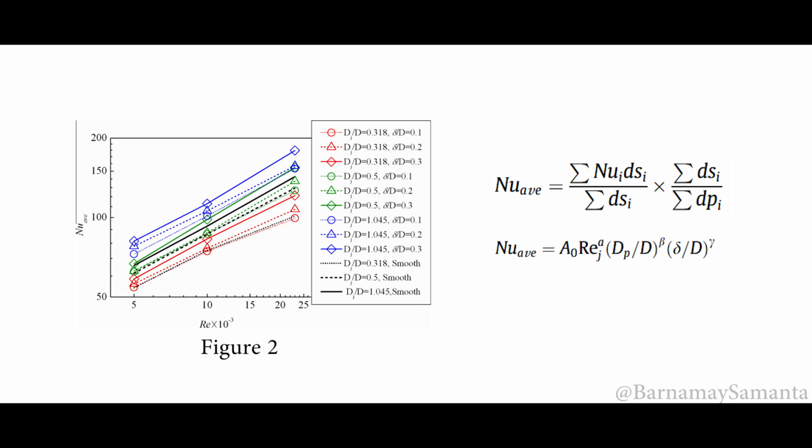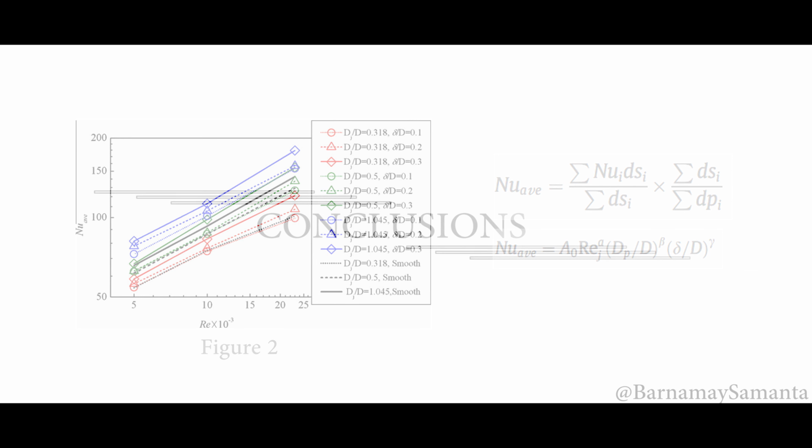The average Nusselt number of protrusion except the above case is higher than that of smooth target surface. For further deduction, the overall improvement of heat transfer for most cases is obtained by the heat transfer enhancement in stagnation region and the increase of protrusion sphere area.